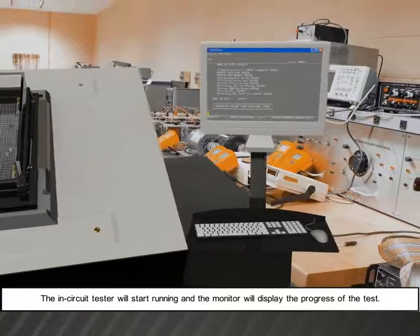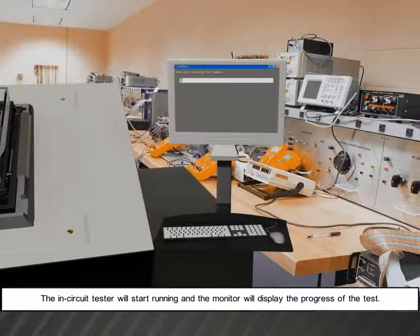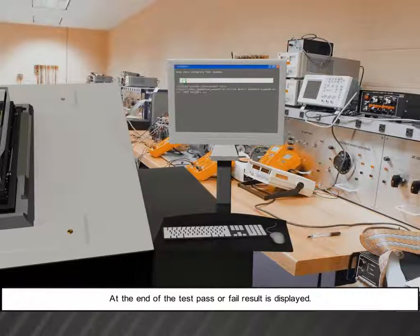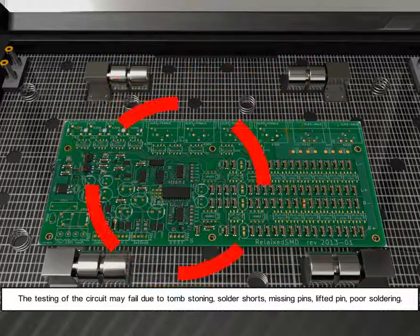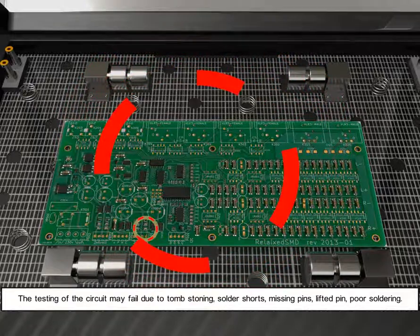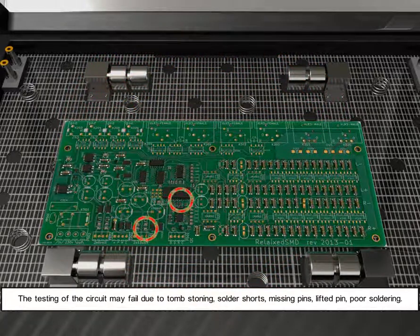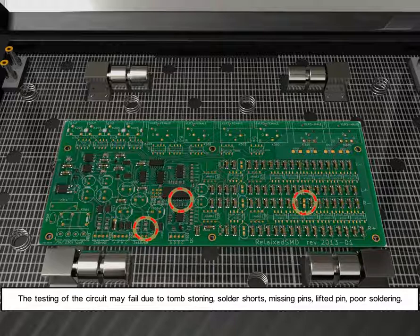The in-circuit tester will start running and the monitor will display the progress of the test. At the end of the test, pass or fail result is displayed. The testing of the circuit may fail due to tombstoning, solder shorts, missing pins, lifted pin, poor soldering.